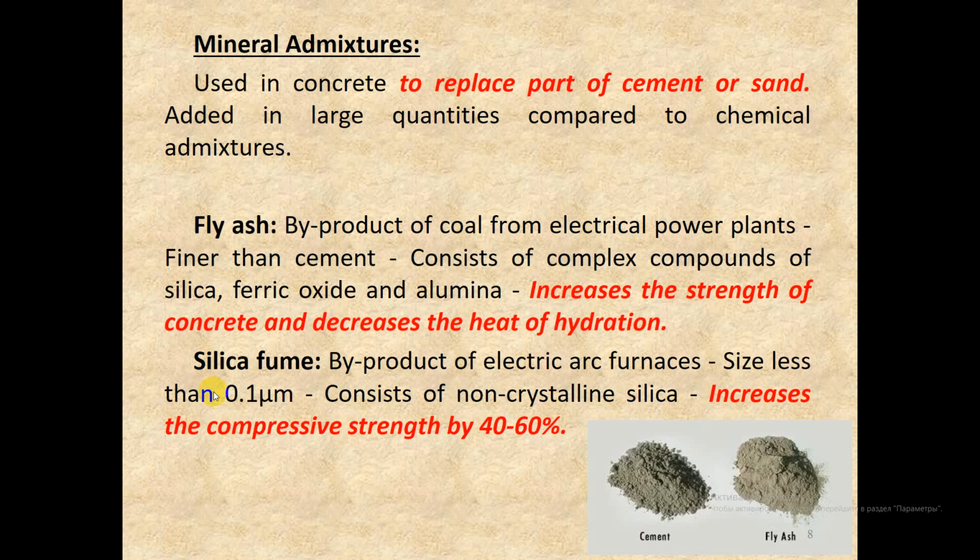Silica fume. Byproduct of electric arc furnaces, size less than 0.1 mm, consists of non-crystalline silica. Increases the compressive strength by 40–60%.